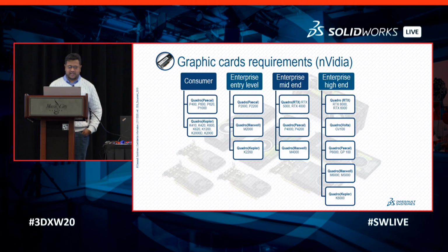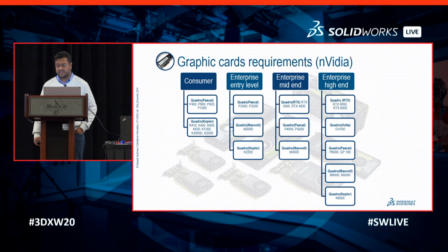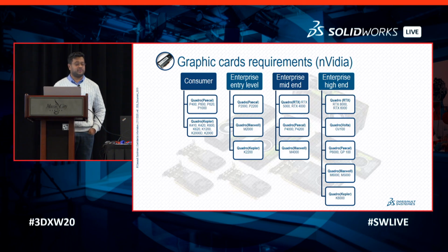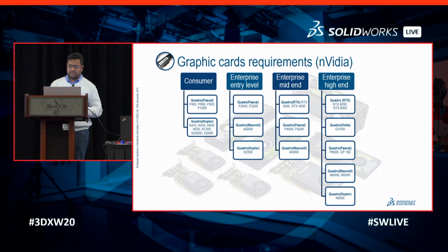All right, so let's talk a little bit about graphics card requirements out here. We consider that there are consumer graphics cards, and then there's enterprise entry level, mid range, and then the high-end graphics card. Consumer grade graphics cards are mostly meant for enthusiasts and hobbyists. They're typically found in low-end devices like maybe Wacom tablets, which have discrete nVidia cards. Consumer grade graphics cards are also GeForce cards that SolidWorks doesn't certify for RealView. And graphics card drivers can improve the performance of the graphics card. So with the low end and next generation graphics card, you can get better improvements in performance.